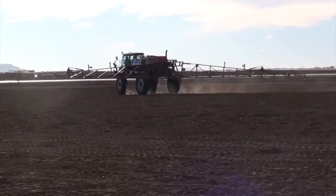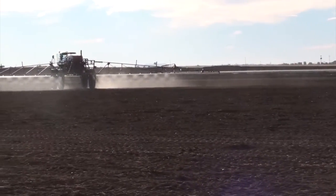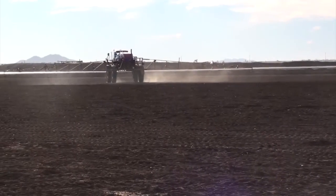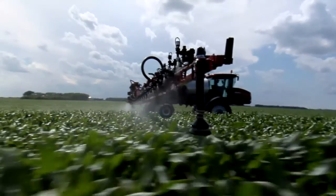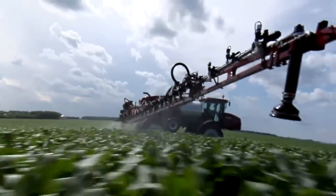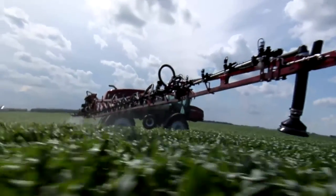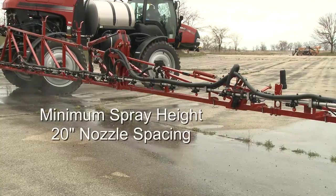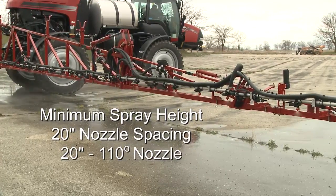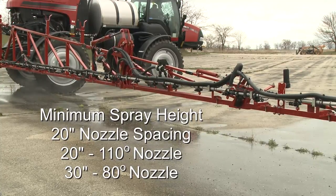Boom height greatly affects the overlap, however, and if the boom height is too low, the pattern will not overlap correctly and will show skips in the field. On the other hand, if the boom height is too high, either over or under application can occur depending on environmental factors such as wind, and will show skips as well. The minimum spray height for 20-inch nozzle spacing is 20 inches with 110-degree nozzles and 30 inches with 80-degree nozzles.